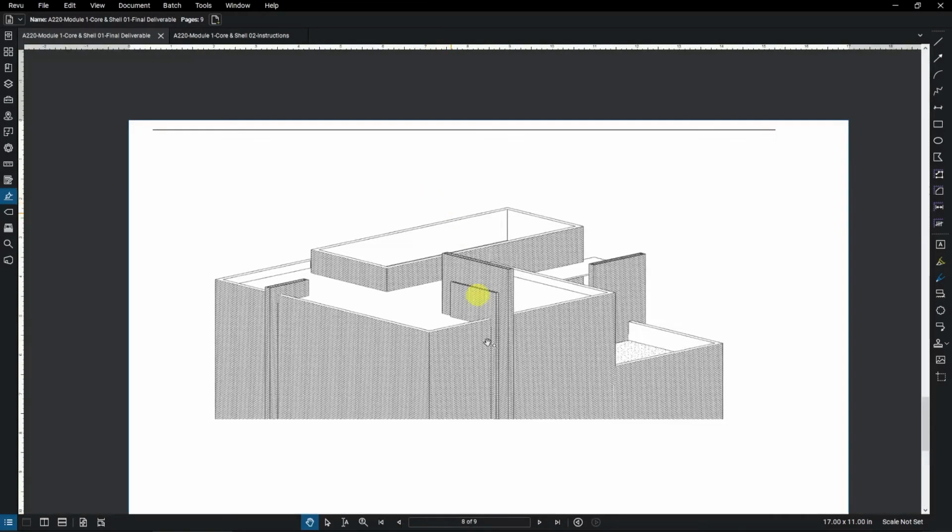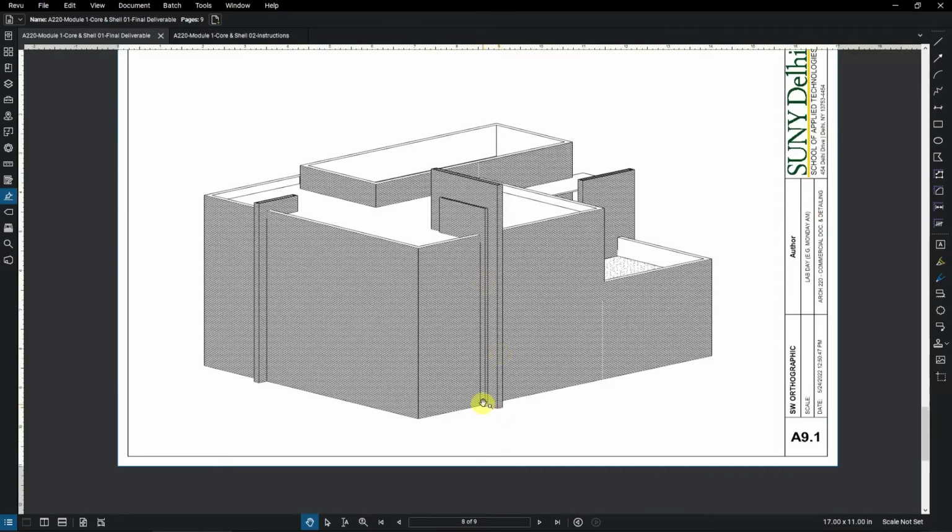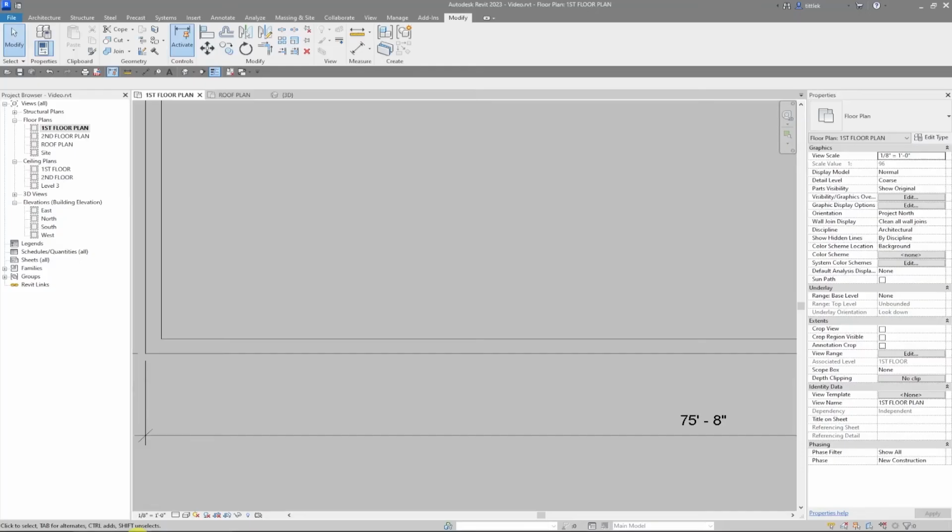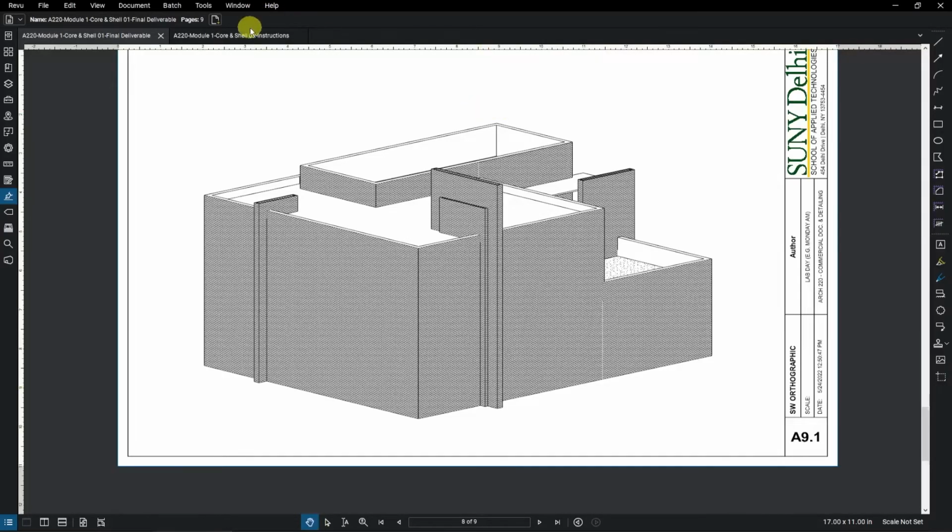You can see that what I'm going to do is create one extrusion, just like I did for this one, that gets me up to the roof level. Then I'm going to create a second extrusion to do this middle portion, and then I'm going to do another extrusion to do both sides, these shoulders. And they're all going to, again, belong to one in-place family. So let's go back to the instructions.